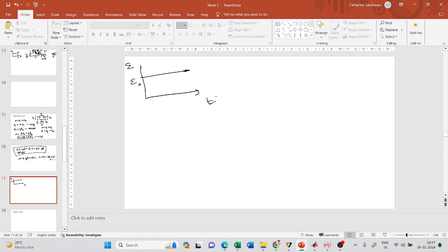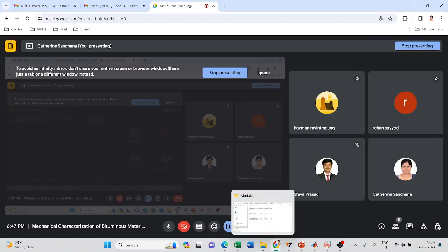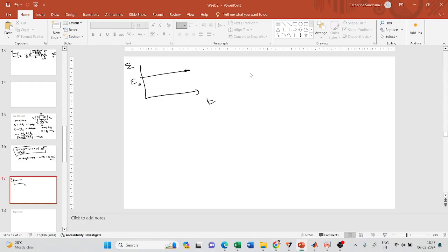Okay. So when I'm subjecting it to a constant stress, constant strain, since the spring and the dashpot are connected in parallel, this will immediately respond. This will immediately give the required definition that I want. But to move or deform this dashpot, I will need an infinite stress at time t equals 0.